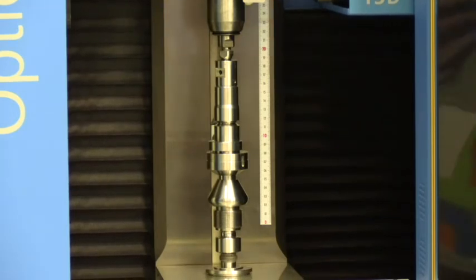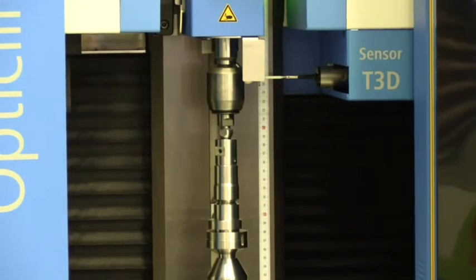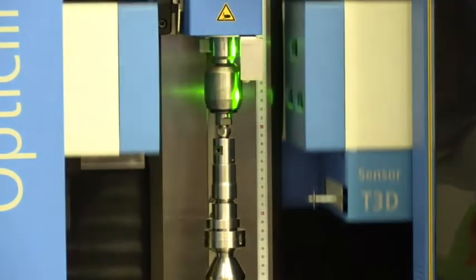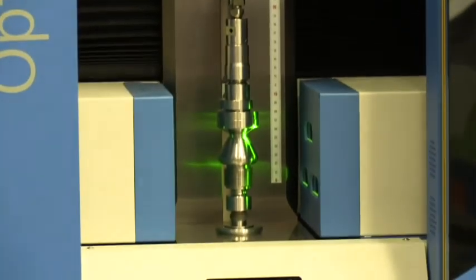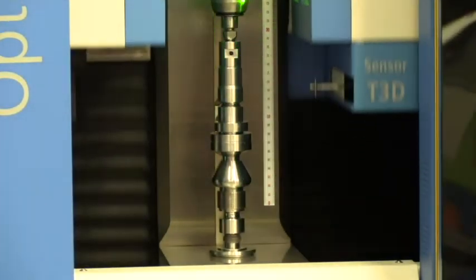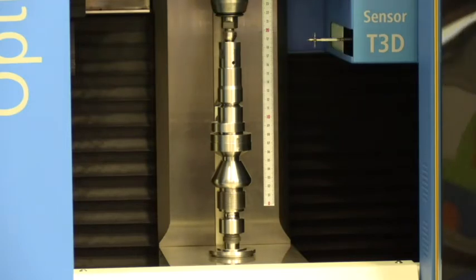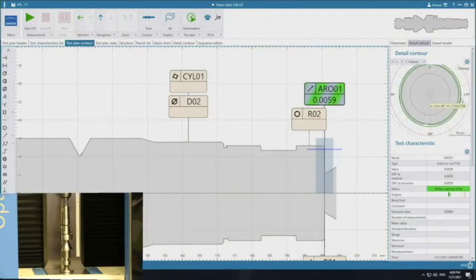So it's just calibrating the touch probe. That's using a little ceramic ball there. And now it's going to use that side and then gently do that run out trace there. Okay, and that's done. Okay, and we can see some lumps on that surface.